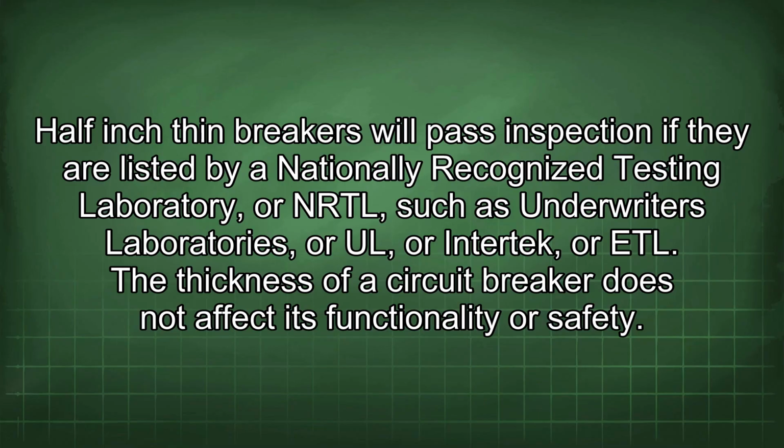Half-inch thin breakers will pass inspection if they are listed by a nationally recognized testing laboratory, or NRTL, such as Underwriters Laboratories, UL, or Intertek, or ETL. The thickness of a circuit breaker does not affect its functionality or safety.